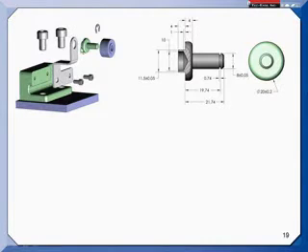Okay, let's go back to this assembly then. Now I look at the stud. And people will say, well, you see this journal bearing right here that the roller rides on? That's a critical feature. It's an interfacing mating surface. Shouldn't that be a datum feature? Not in my book. I ask what locates and orients the stud in its assembly.